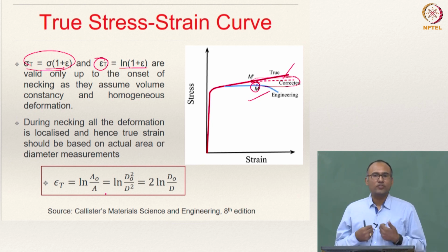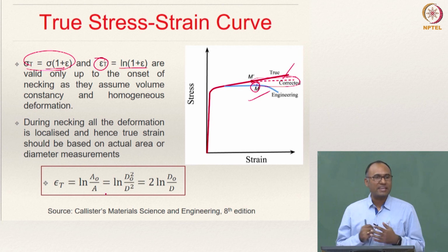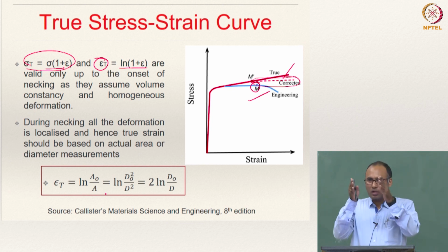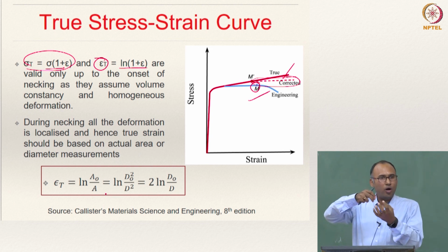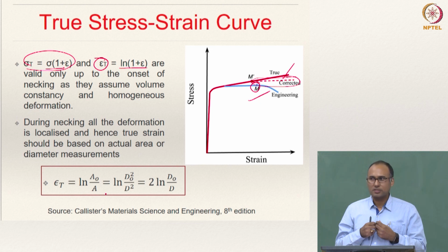Okay, so that is typically what is observed in a ductile material: the localized deformation takes place. That means typically in a ductile material, this phenomenon called necking happens. So the local cross section suddenly starts decreasing. This means all the deformation is localizing in that area. That is why it is called localized deformation. And eventually failure happens there.